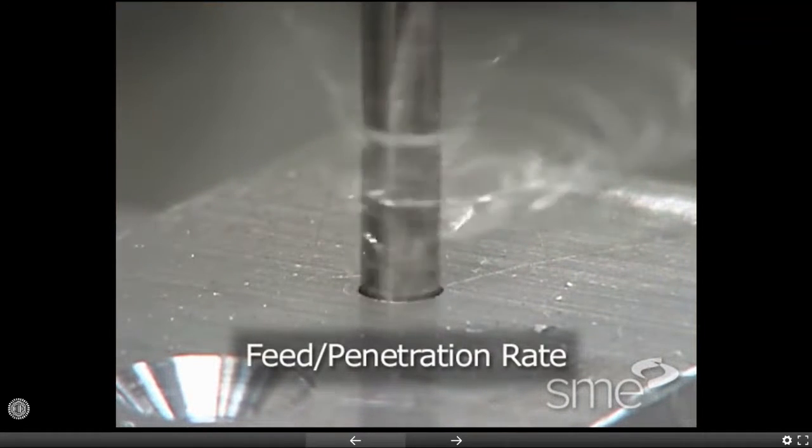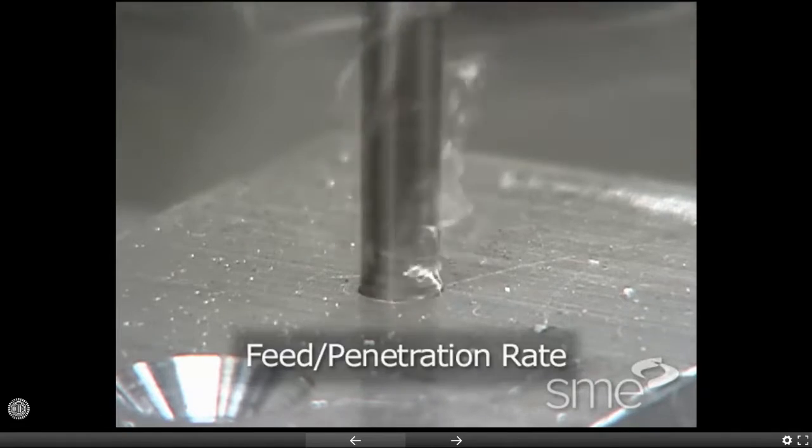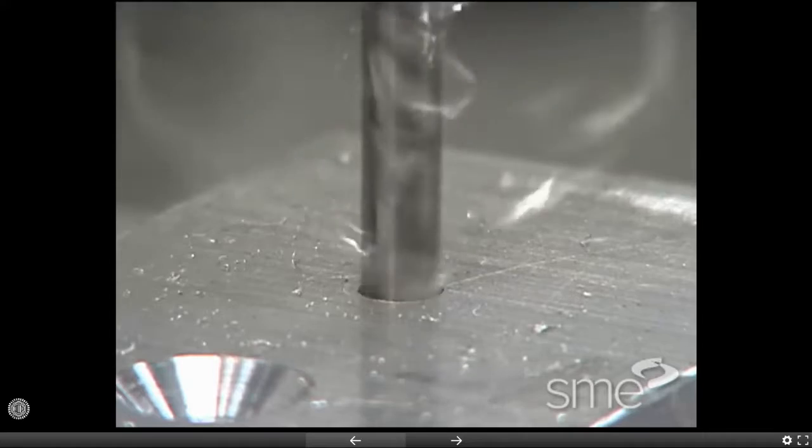As a rule, the harder the material being drilled, the slower the speed used. The feed or penetration rate is a distance per unit time and is expressed in inches or millimeters per revolution of the drill, or in inches or millimeters per minute.